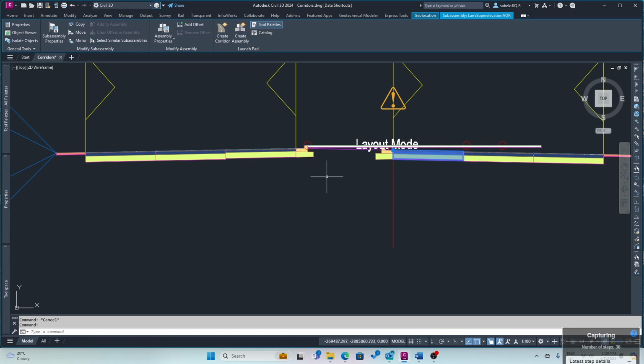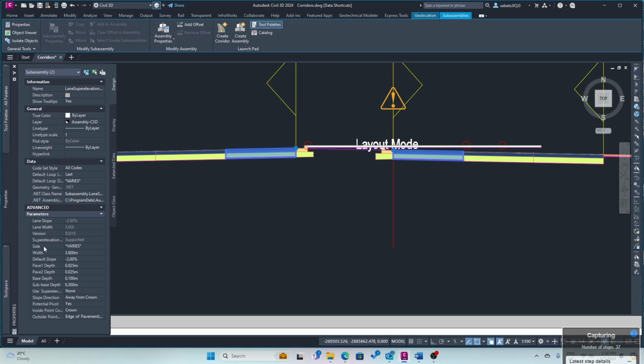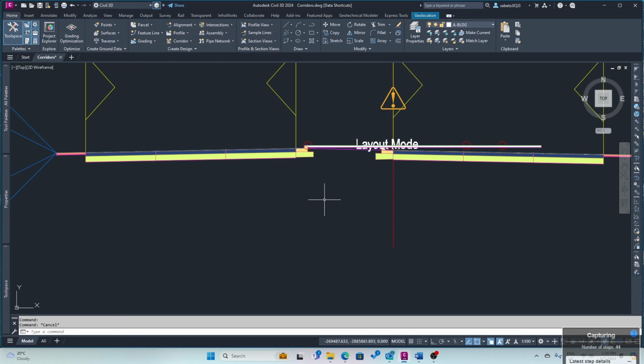We now select both these 2 new lanes, and then we come onto the properties, and we just want to change some of their properties here. I think our pavement depth here was 0.02. Adjust that. One was 15.3. That's okay. So now they both are matching up.